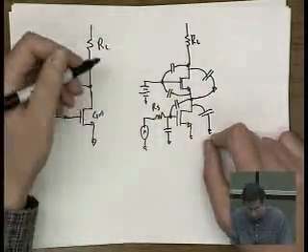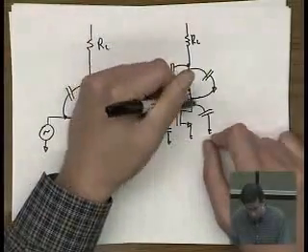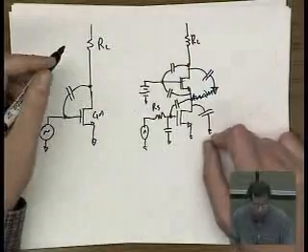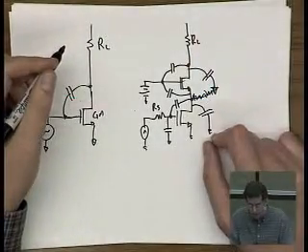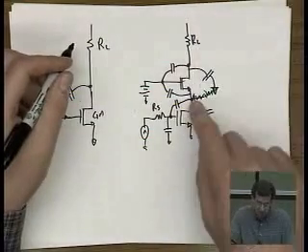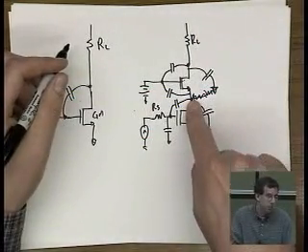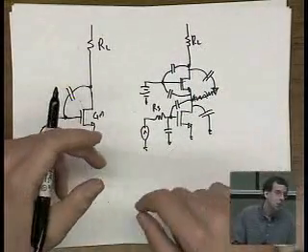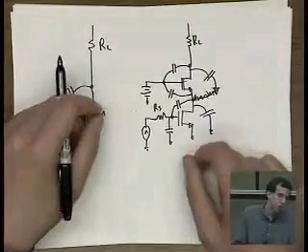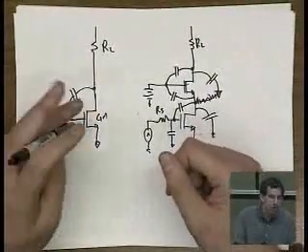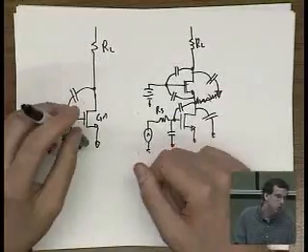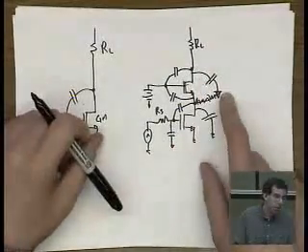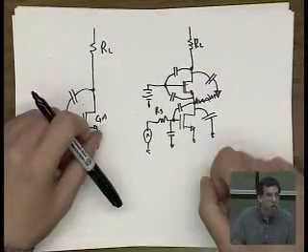And I think actually in my solution set, I kind of ignored that and did this. And by and large, that won't hurt you very much because at least looking from the output, this is a low impedance node, so it's a low swing node, so it can be approximated as ground. So you can basically just tie that cap to ground. The reason why we tied source to bulk was just to keep VTs the same. In reality, that's not what's going to be done because that will introduce other issues. So in general, the drain bulk capacitances, the bulk will be a small signal ground.